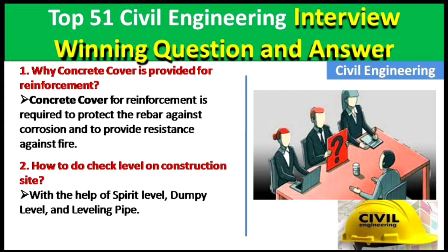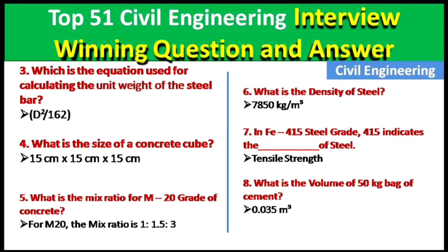resistance against fire. Okay, now the second point is how to check level on the construction site. Okay, so we check the level on the construction site, it means the slope of the construction site, with the help of a spirit level, dummy level and leveling pipe. Okay, so now let's move to another point.